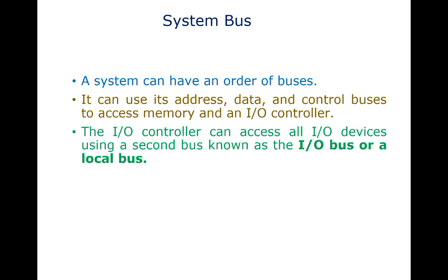The next is the memory read operation. The basic sequence of a memory read operation is: place the address, then the read signal is issued. The memory then accesses the specified address, and the data is placed on the data bus.